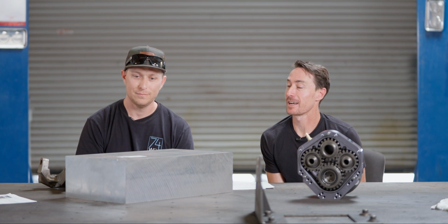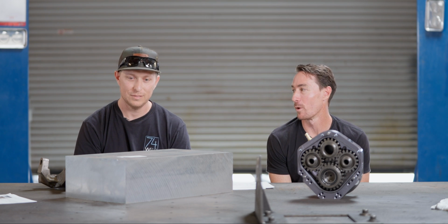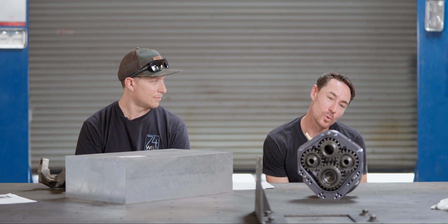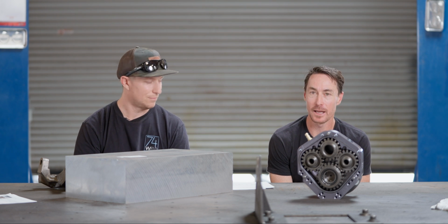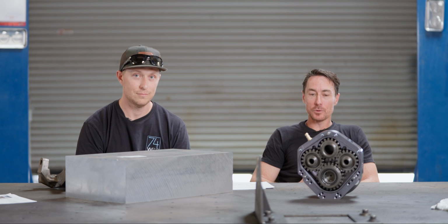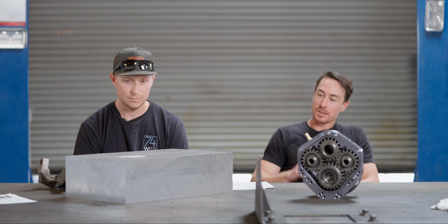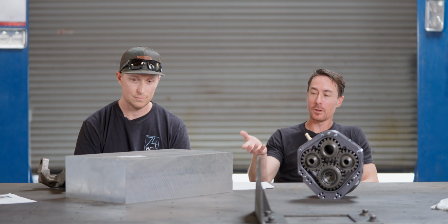Well, and also I guess I should clarify, because I'm staring at that block of aluminum, and it says Kaiser Select 7075-T651. We will not dive into tempers of alloys today, but that T651 refers to the heat treatment that is done post rolling at a mill.